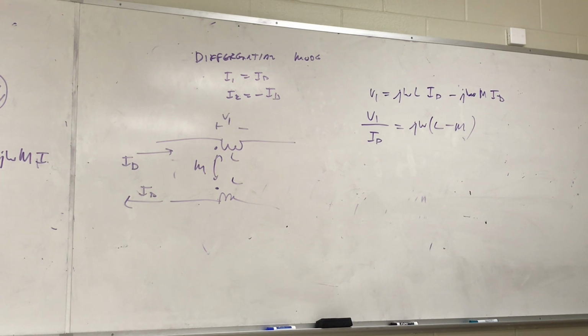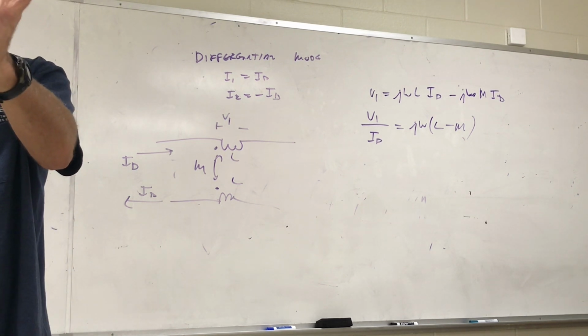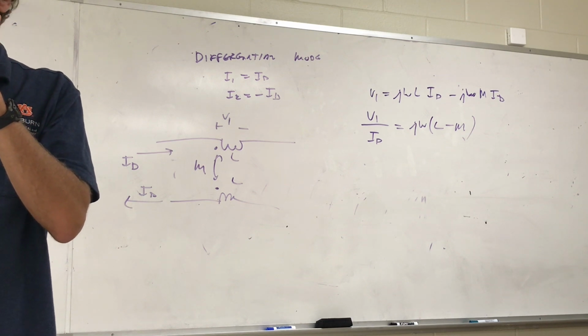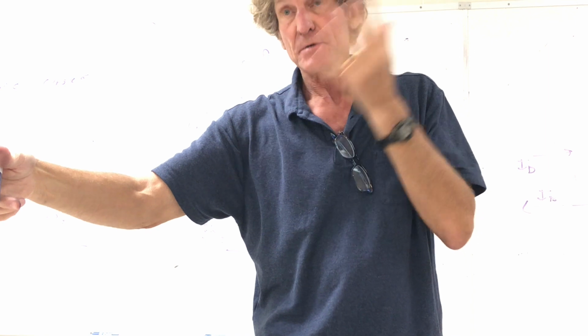It'll block common mode. This is especially important when you're dealing with any kind of wiring that could have a ground loop induced in it, like whenever you get coax cable running all over the place, you know what I'm talking about, right? You get huge lightning strikes nearby, it'll induce a magnetic field that's very large in there that will cause a ground loop if possible, it usually does.